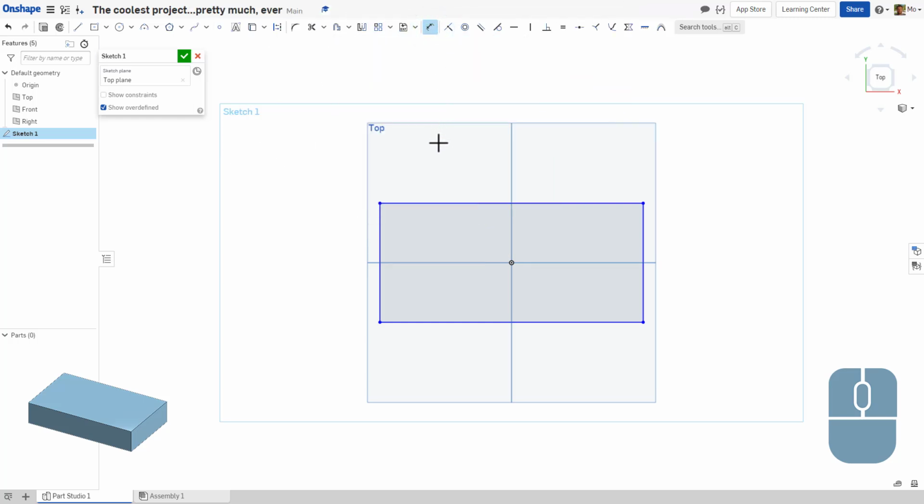Let's click on this, and we now have our crosshairs again. If we hover over one of the edges and click on it, and pull our cursor away, you'll notice that this little balloon comes up, attached to your cursor, with the numbers 5.481 inches tagged to it, right? We need to drag this somewhere to drop it and place it so that it can start labeling and dimensioning our part. But here's where I want you to take your hands off the wheel real quick and watch me do this, because this is a common pitfall that a lot of people make.